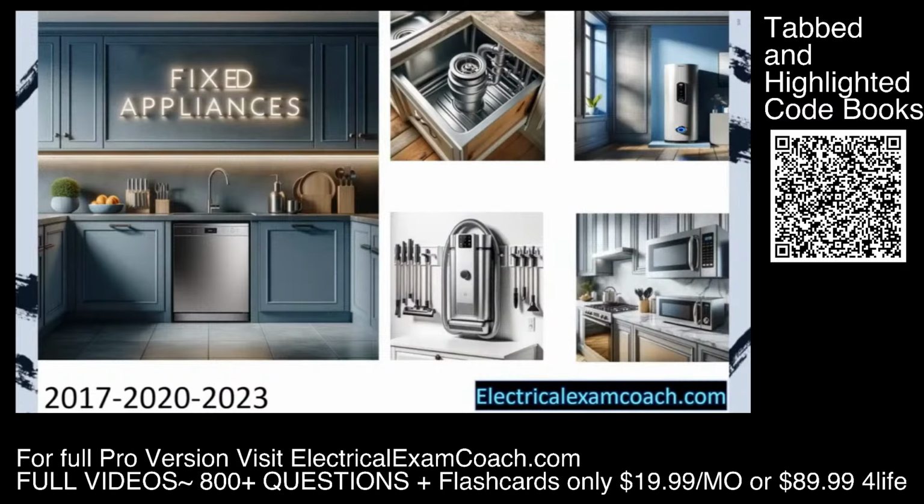You'll notice in this bottom right-hand picture that there's 2 microwaves. One is not fixed, and the other one is fixed. And when you fix it to the wall or fix it so it can't move, either with plumbing or mechanical vents or anything else, it now becomes a fixed appliance, and there's a special way that they calculate them when doing a whole home load calculation.